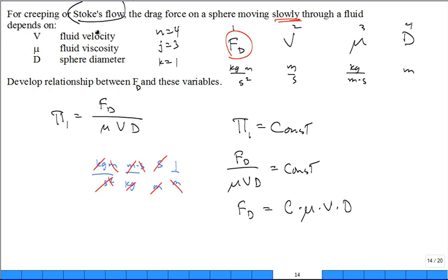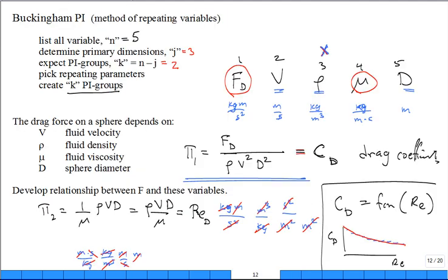All right. There's one thing I forgot to do. Let me back up and see if I can fix it right away. Sometimes people will put the drag coefficient and they'll put 1/2 right here. Why did they put 1/2 right there? They did change the definition of the drag coefficient by putting a 1/2 there, but they put a 1/2 there because 1/2 rho v squared is also called the velocity pressure, the dynamic pressure, right?